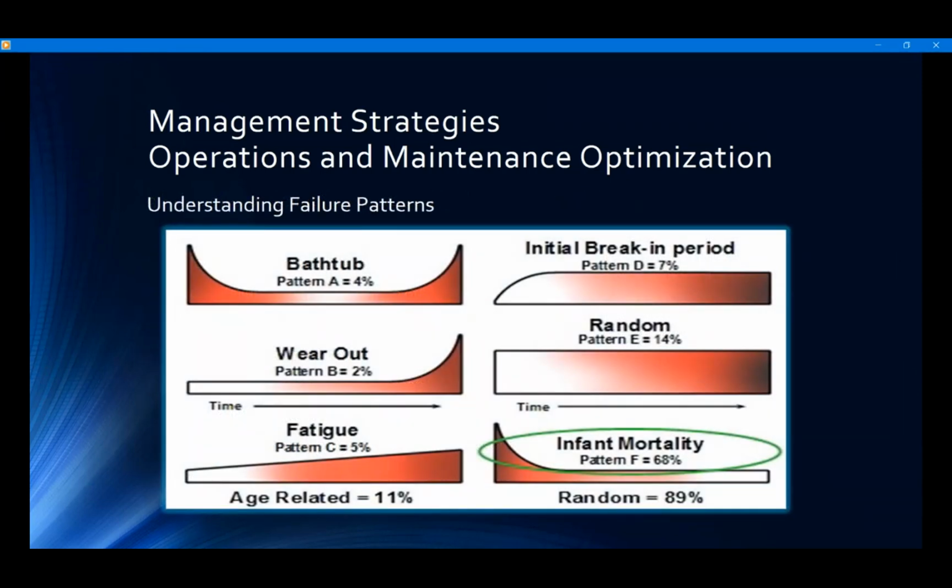This slide gives us a good look at failure patterns and understanding failure patterns. Random failures. The term life cannot be used to describe the point of rapid increase in the likelihood of failure, as there is no specific point. These are the flat parts of a failure curve. These types of failures occur due to some introduced defect. Infant mortality. The term life cannot be used here either. Instead, there is a distinct point at which the likelihood of failure drops dramatically and transitions to a random level.